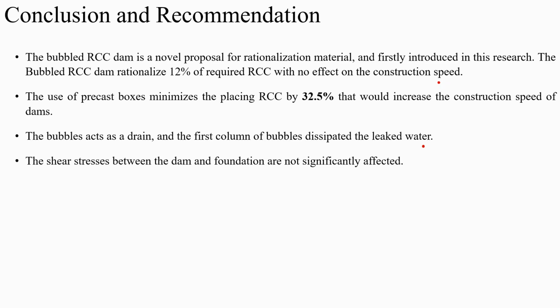The bubbles act as drains, and the first column of bubbles dissipates the leakage water. The shear stress between the dam and foundation is not significantly affected. However, in time history analysis or seismic analysis, stress increased, but still within the allowable range.